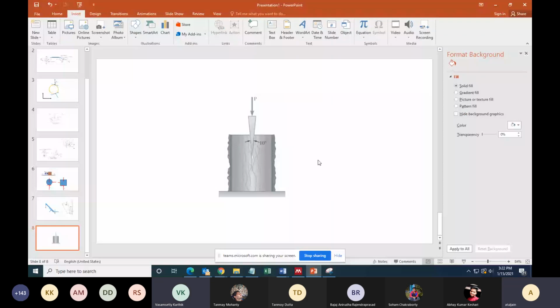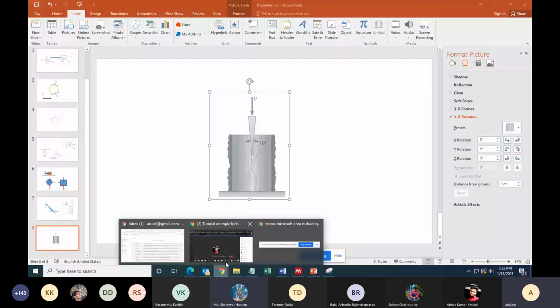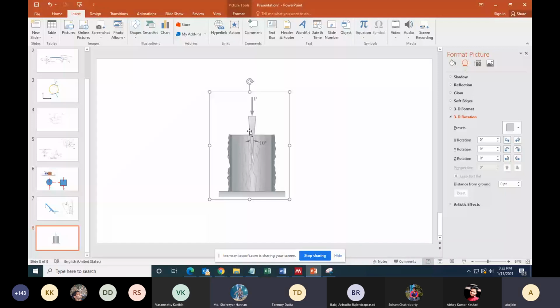Remember, there is a very interesting story, and you will learn that too. I think after studying the wedge, you will find that the P required to push it in is much lower than the P that will be required to pull it outside, due to friction. So P will be higher when you are trying to pull it out. So I think push it in.